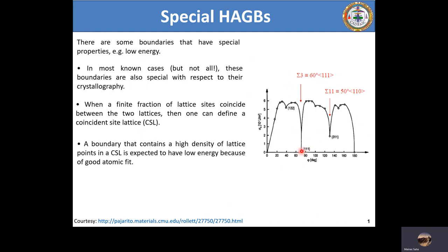The other thing I can tell you is that in the case of aluminum, there is a very rare chance that you will see a twin at room temperature, because aluminum is a high stacking fault energy material. But there are chances that you are able to see twinning even in aluminum.